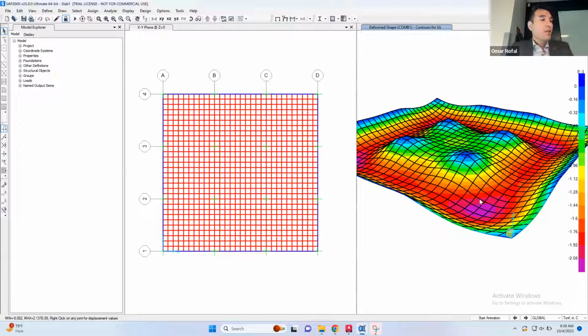But let's see if you guys remember, when we talk about the bending moment for a slab, it's not like a beam, it's a 2D element. A beam is like a 1D member. It just has a bending moment in one direction. It doesn't have a second direction, but two-way slabs, let's talk about two-way slabs. So do you guys know what is the difference between one-way slab and two-way slab? What is the difference? The load distribution, which alters the values of the moment.